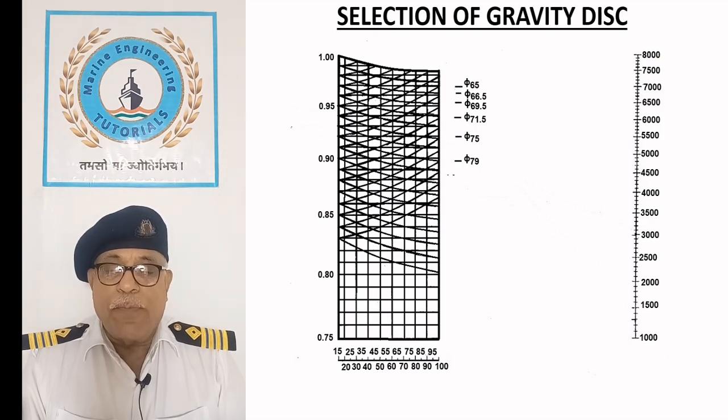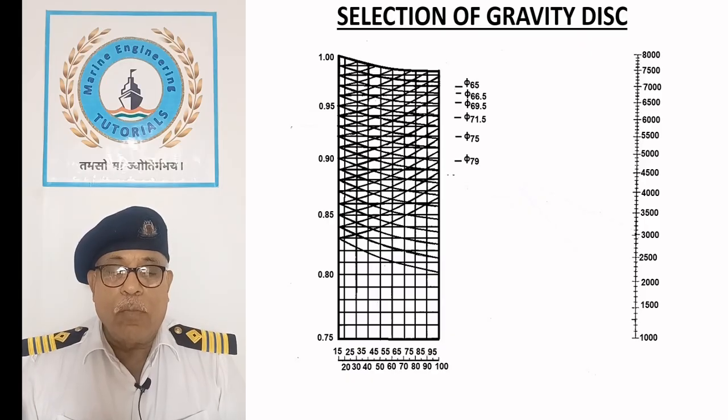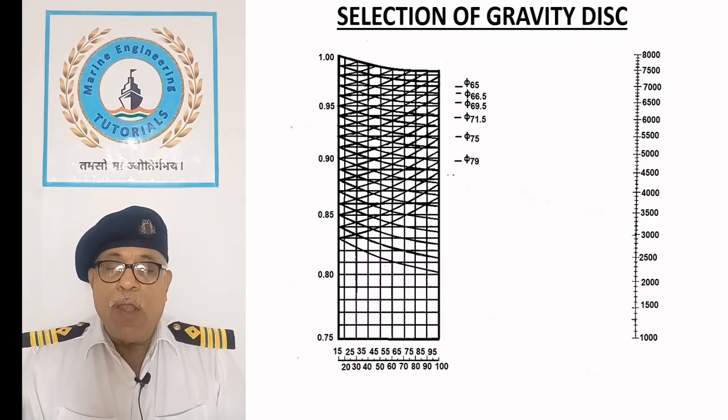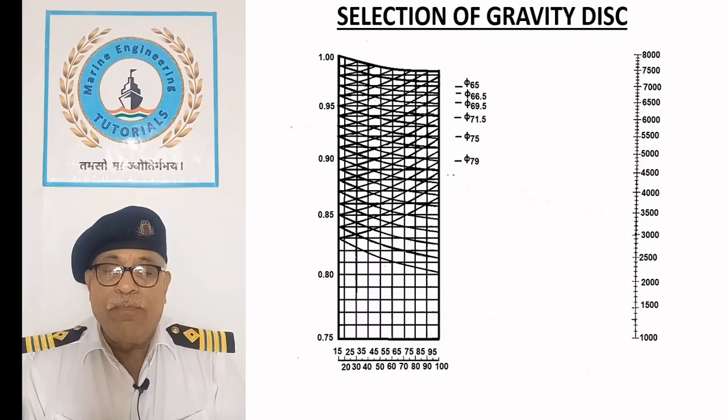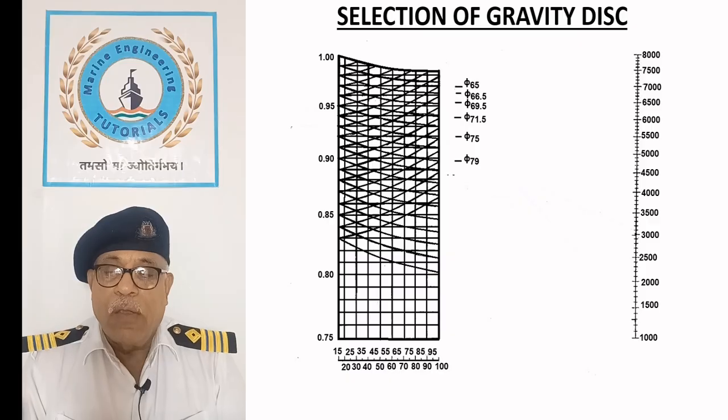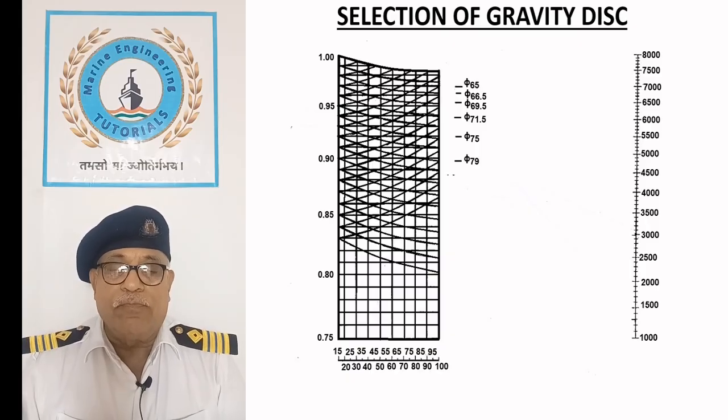Thus, separating temperature must remain constant. The oil feed rate in a purifier should be optimized for best performance. Feed rate should be adjusted to provide 5% above the actual fuel oil consumption so that fuel oil level in the service tank is steadily maintained.